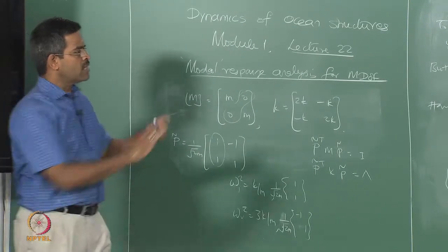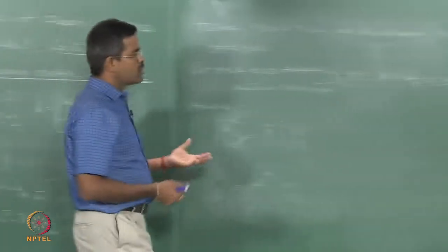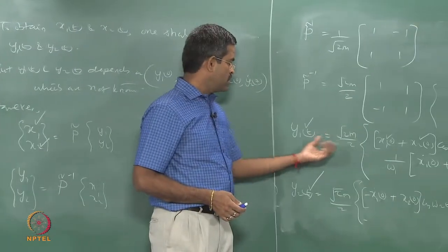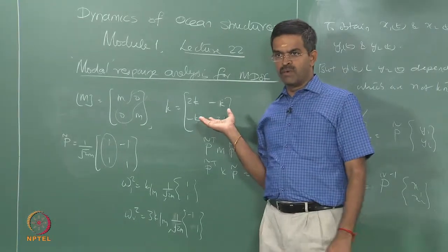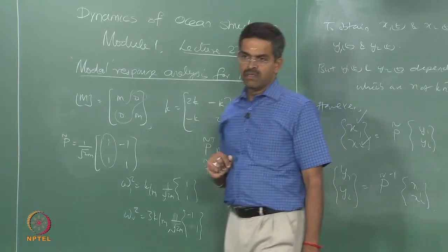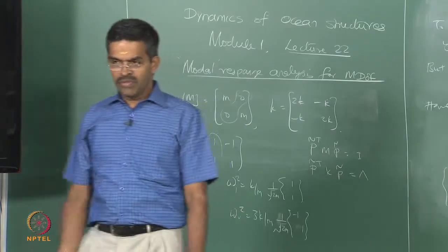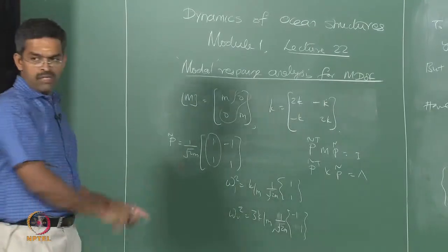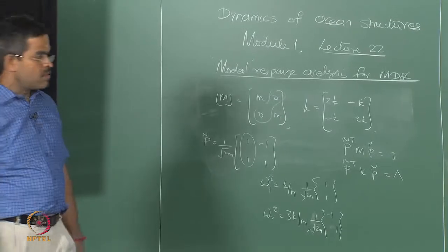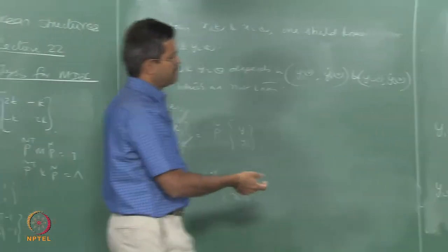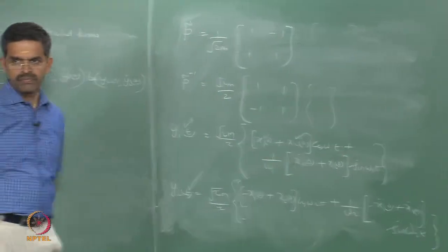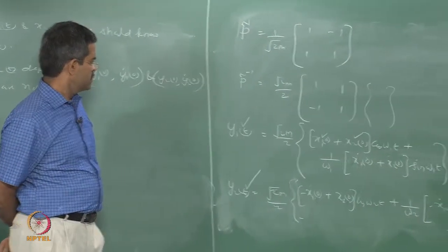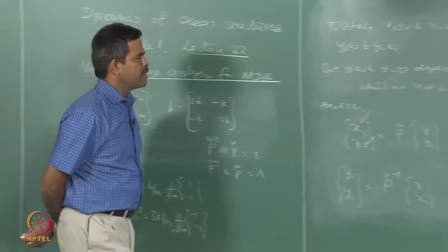So, we have never solved any matrix here at all, we simply used only the single degree freedom system knowledge and found the solution for a 2 degree freedom system problem without actually solving any matrix. This will be easy if you have a large matrix, because this is repetitive. If you know the initial conditions, this is repetitive, you can plot.